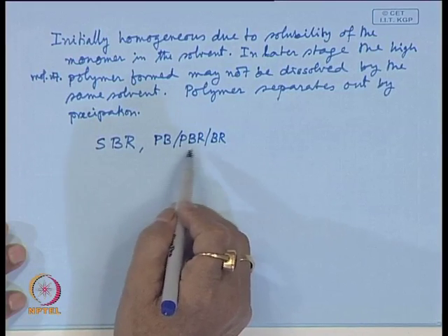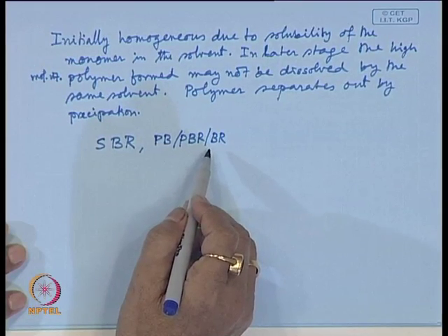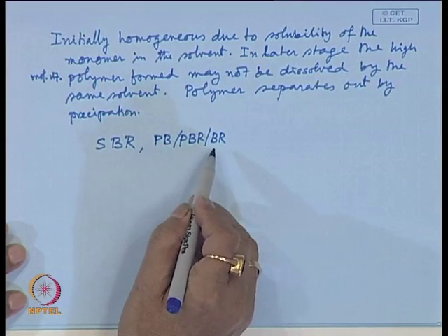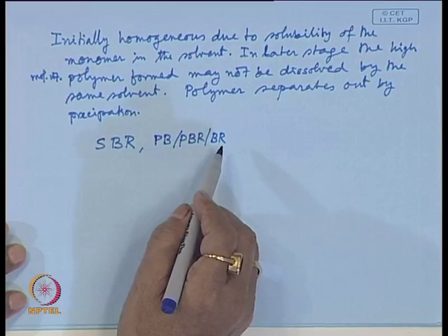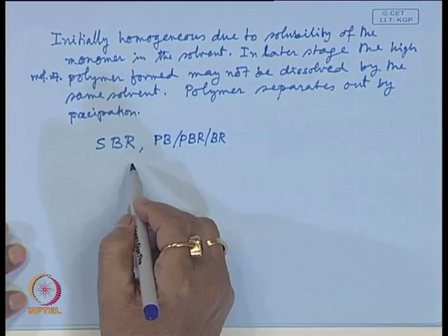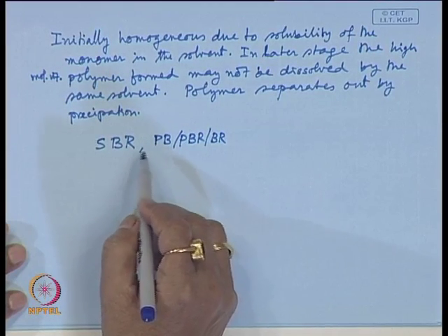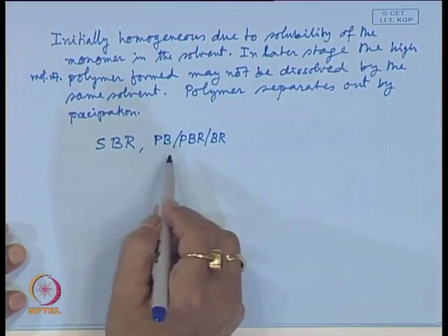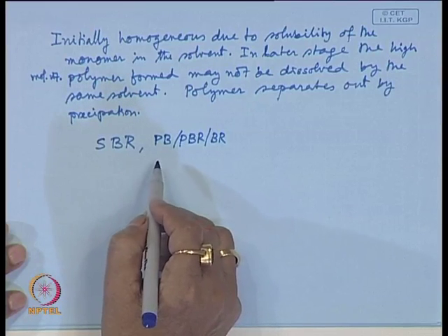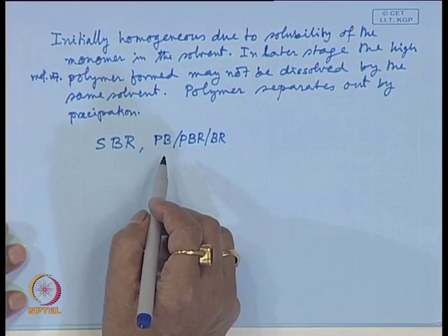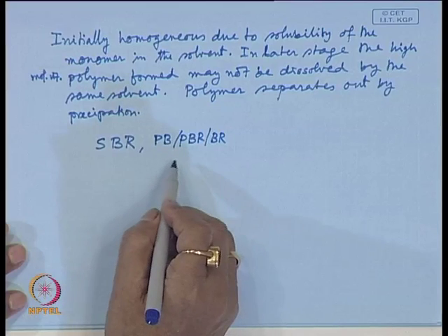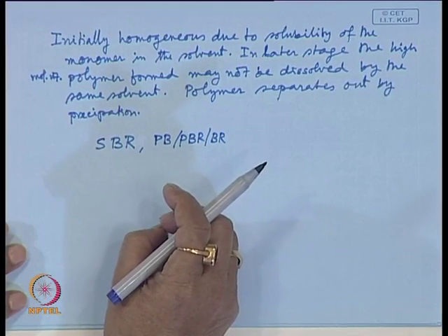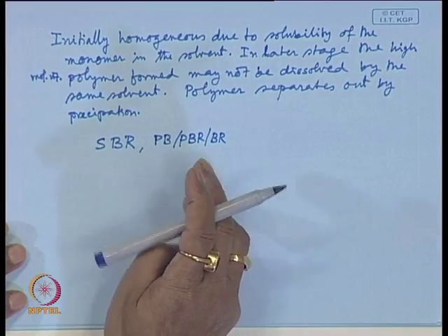The polymer is same, polybutadiene rubber. Now, this styrene butadiene, polybutadiene or other polymers, they are made by solution process or suspension process. Normally these polymers are not synthesized by bulk technique, they are polymerized by solution technique, solution SBR, solution BR, etc. Their grades are mentioned as solution SBR, solution BR, like this.